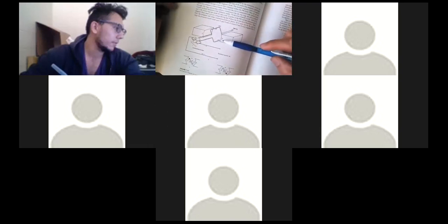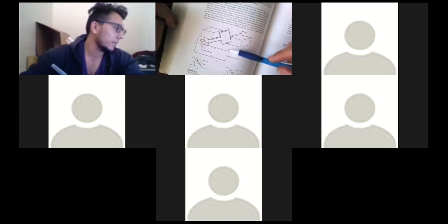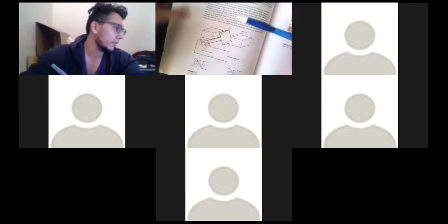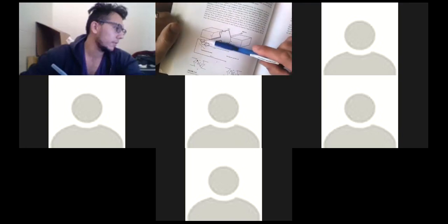This is a DC motor, so that's battery powered. So there's a commutator. The function of commutator is reverse the flow of current direction. So the torque is always one direction. Otherwise, the torque will alternate in directions. So this is actually a converter.